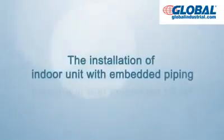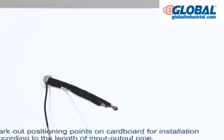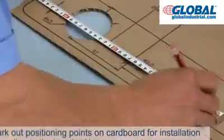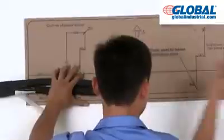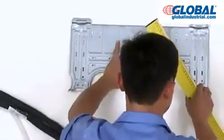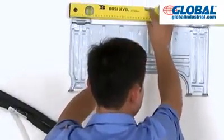The installation of the indoor unit with embedded piping. Firstly, mark out positioning points on cardboard for installation according to the length of the input-output pipe. Mark the position on the wall with the cardboard according to the position of the embedded pipeline and the cardboard positioning points. Determine the installation position of the indoor unit.